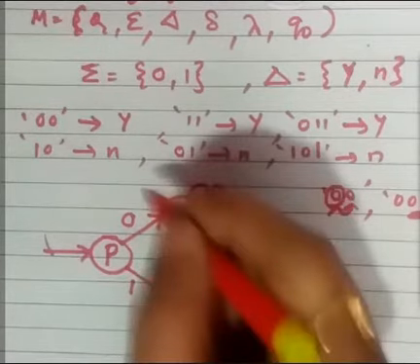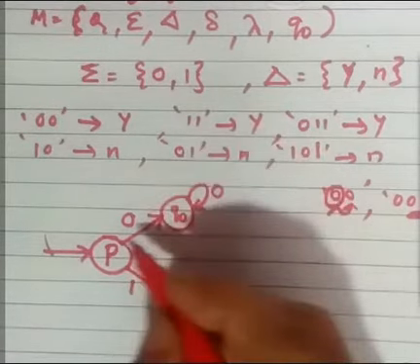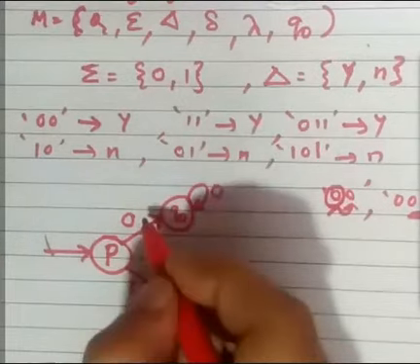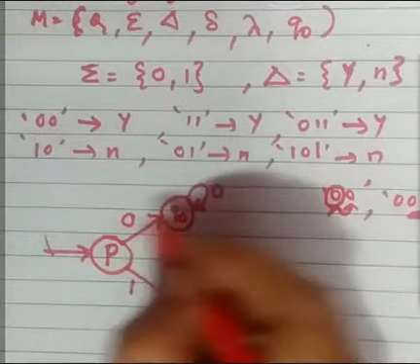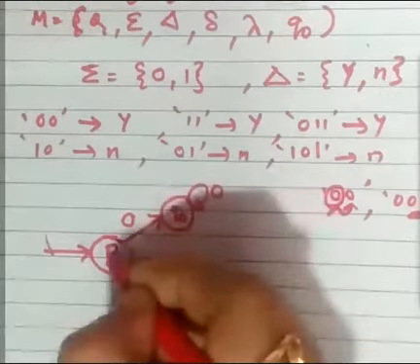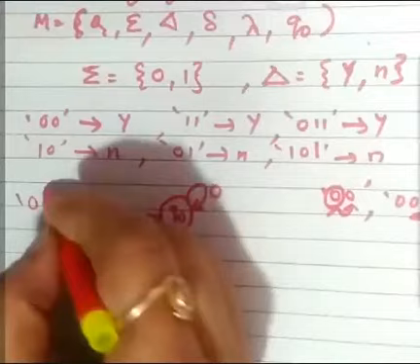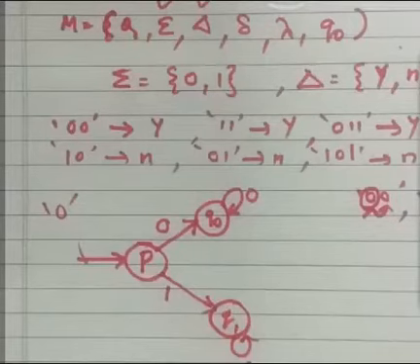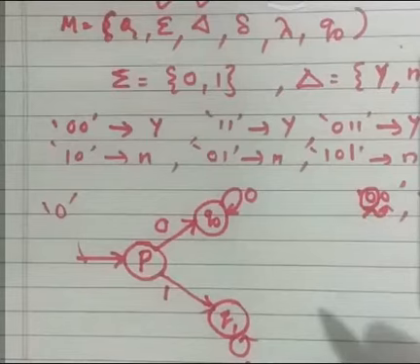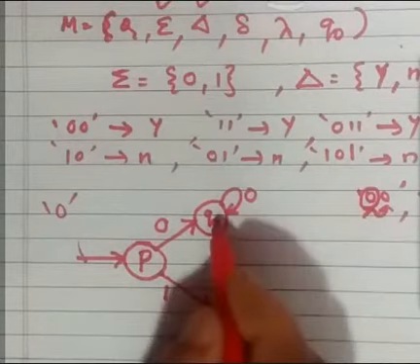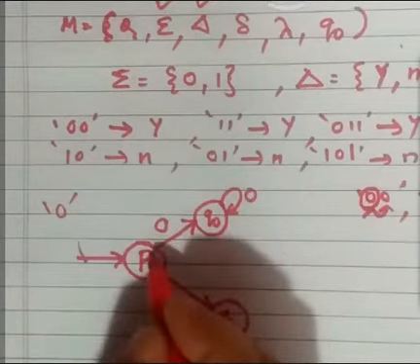Okay. Now, when will I get the output as yes, if I am moving only, or if I am getting input as only 0? What is the output expected? Now, this is not a Moore machine. The output is not associated with the states. The output is associated with the current state as well as the current input.